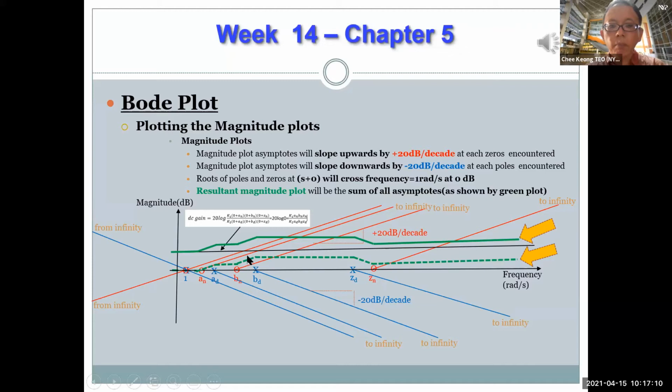Let's talk about the S at 0 and S at non-zero for the numerator, which is the 0, and the denominator, which is the pole, right? One is at origin and some are not at origin, all laid out in this relative position. So right now, your goal, remember, for the 20 log magnitude scale, is basically to add or subtract all of this, right? So you have one pole going down, one 0 going up. These two add together, you are flat, basically from all the way from negative infinity until this point, right?